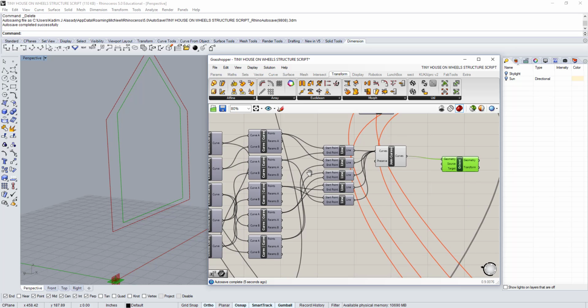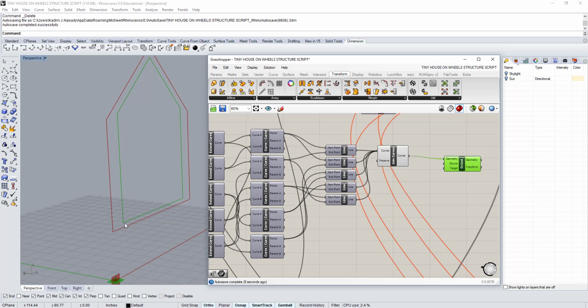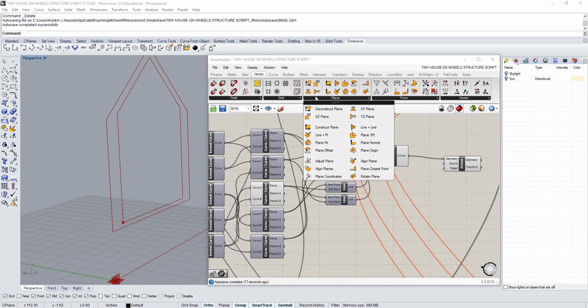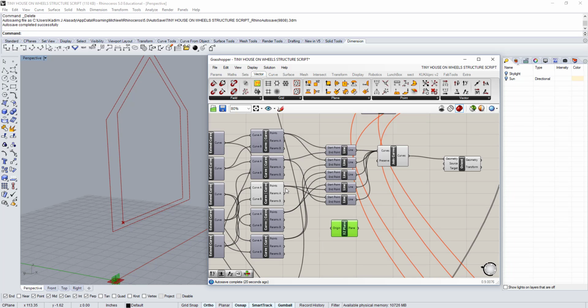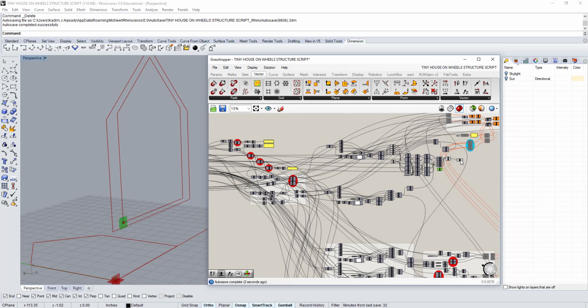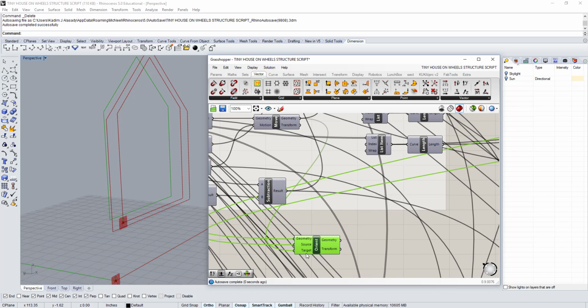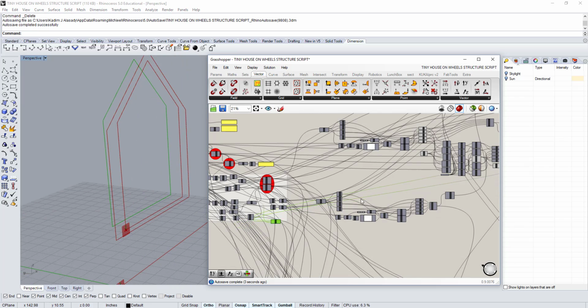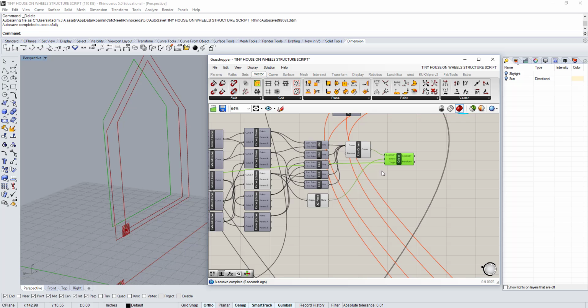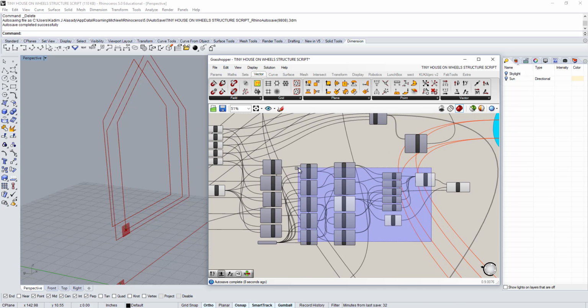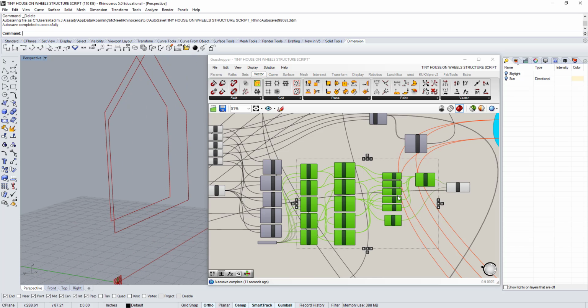So the initial plane is going to be an XZ plane about this point right here. So we want to find out which point is that one. Might be this one. There it is. So what I want to do is go to Vector, Plane, XZ Plane, and plug a plane into that origin right there, and then use that as your source plane, and then your target plane is going to be this transformed plane that we did way back when, and there it is. So this is the new transformed oriented geometry. So now let's turn off all of these, and now we have these 2 curves.